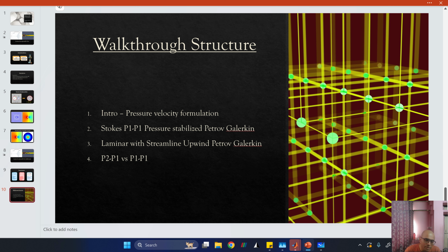So now we'll just use the same thought process on Navier-Stokes, and I'll also provide the codes for both of these, and this would probably make it easy to visualize. We'll see our problem, which wasn't converging without SUPG, will converge once you have put SUPG into the picture, and we'll also show some validated results against that. We'll just look at the lid driven cavity in this particular walkthrough, because it's a very simple and straightforward problem.